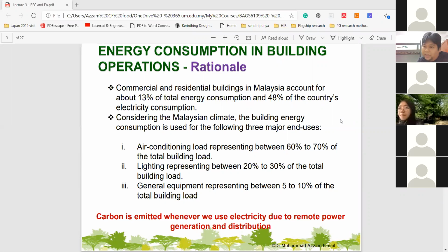So for artificial lighting, if you still have the old incandescent lights, or even fluorescent lamps, go to Mr. DIY and just buy new LED lamps. Easy enough to fit. Even the old fluorescent light casing can still be used with new LED light bulbs, but you need to disconnect your ballast.